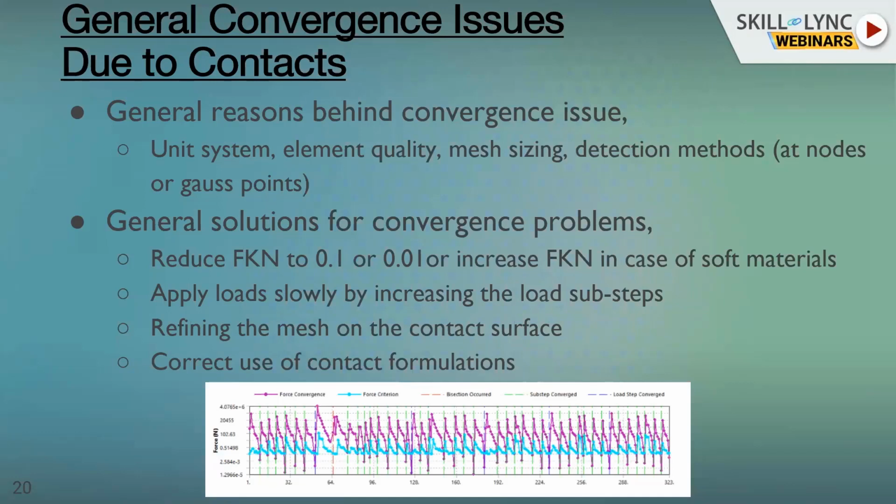We'll discuss that now. So the first is the unit system. Generally check while solving. Ansys Workbench has made it very easy, so you don't have to worry about the units when you are modeling any problem. In other software, you need to keep the unit system in sync. The simulation software doesn't have any standard units of its own. What we need to do,